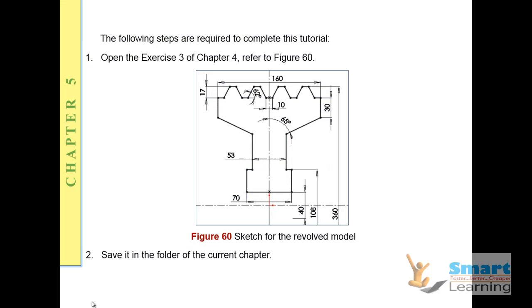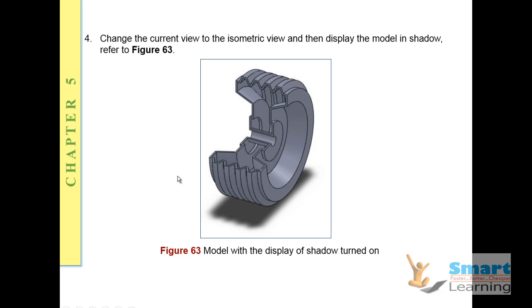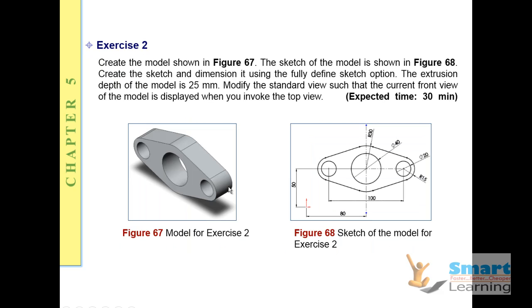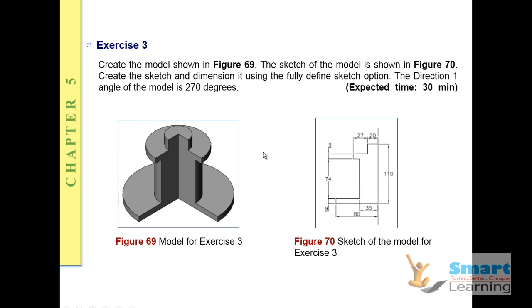A couple of exercises you also have, that you can see. So after creating this particular sketch, you try extruding this, and these are the details which you have, and this you can get from your exercise folder. Just open it and try creating by using this sketch and extrude this. Just like that, you have another simple sketch, which you can try for creating this. So capture this and extrude with respect to the required direction, and you can give arbitrary values.